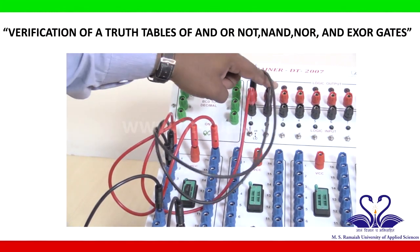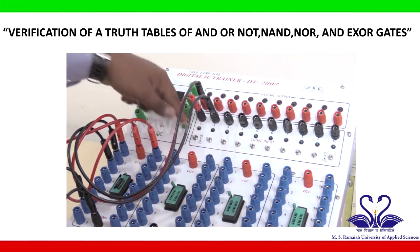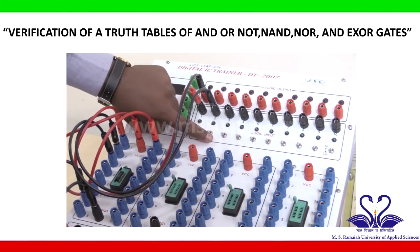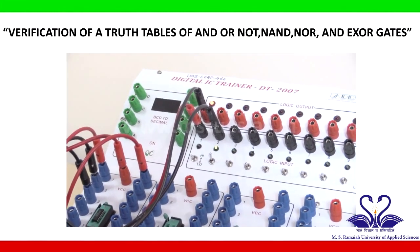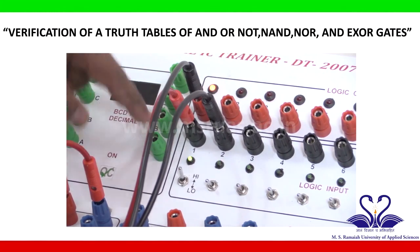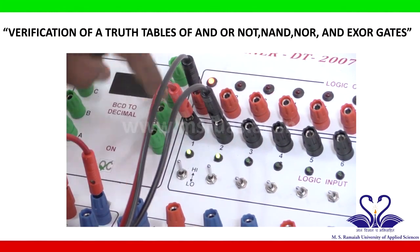So we have 2 inputs and 1 output. Now turn on the digital IC trainer kit. So let us verify the truth table of OR gate. For input 0 0, output is 0. Now we'll make 0 1. Output is 1, that is light glowing. Now we'll make 1 0. For 1 0 input, output is 1. Now we'll make both 1. Both inputs 1 1, output is 1.